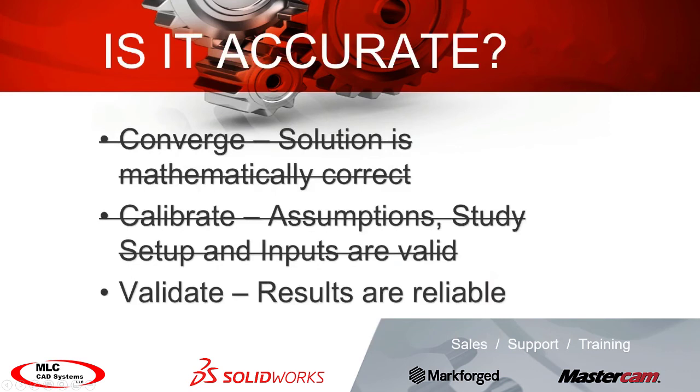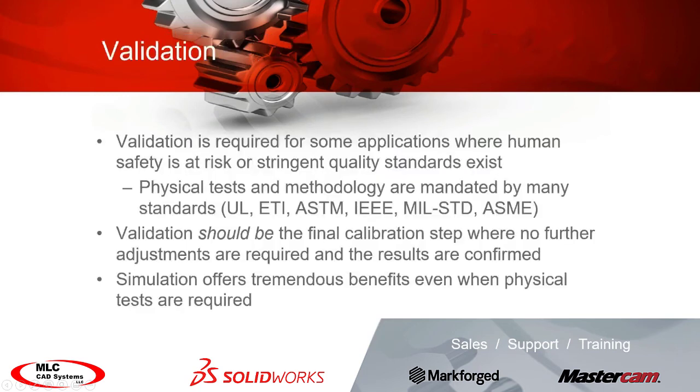Which takes us to the last step, which is the validation step. Now, we need to make sure that these are right, especially if we're going to be building 1 million units. It's also possible that it's required. For some applications, some ratings agencies or quality standards require that you have a physical test, and they lay out the methodology very specifically. The validation step should be basically the final calibration step, but no further adjustments should be required.